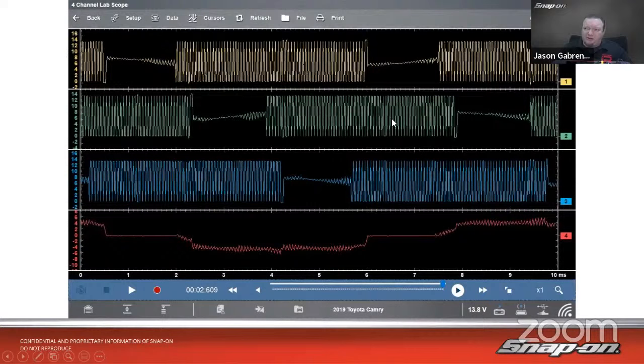And they are 120 degrees offset because of a 360-degree circle. Split it into 3, you get 120. And then we can also see the amperage, the current flow. We get positive current and negative current. So this one I needed 4 channels. You could do 3, or you could just do 1, 2. You could do voltage and current if you wanted to, but you wouldn't be able to compare the different magnets or the different windings to each other.